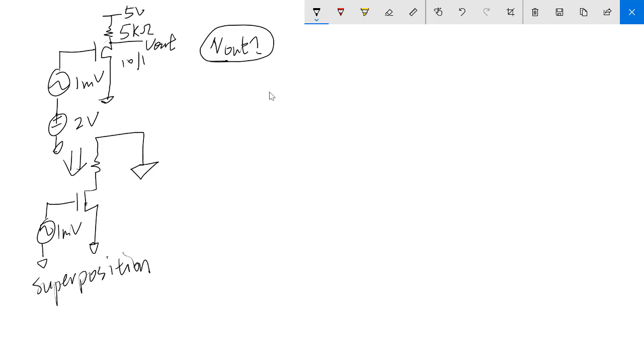Because we know the AC signal is something like when you are working in the lab, you activate the AC coupling, right? If you do the AC coupling, it's only going to show you the AC signal, but not the DC offset. If you're doing a DC coupling, it's going to show you everything. Sometimes the signal is out of the monitor, it has a huge DC offset, and you do want to remove it before you can see anything in your signal.